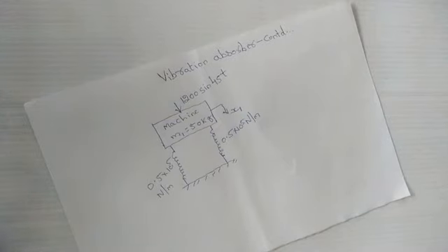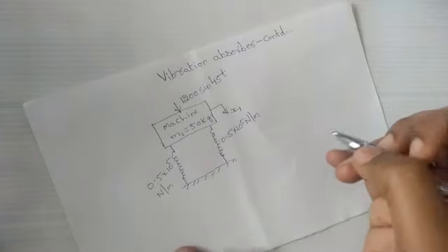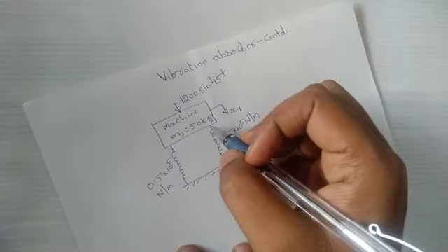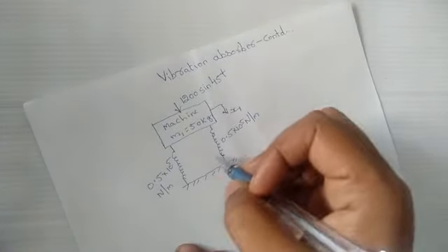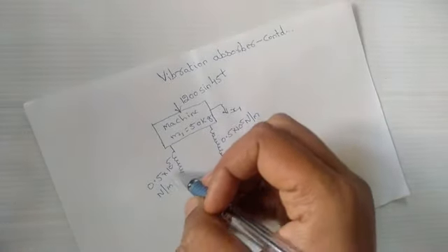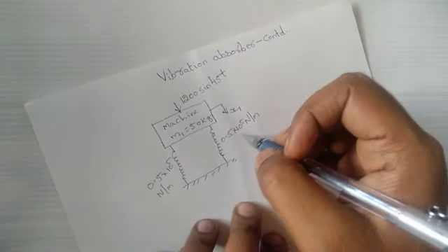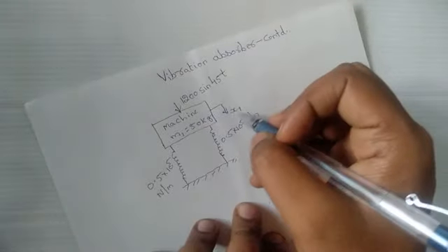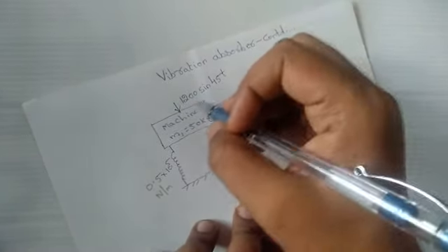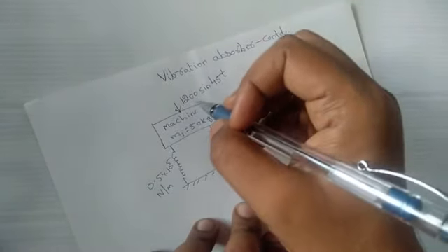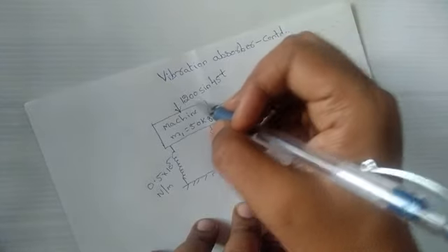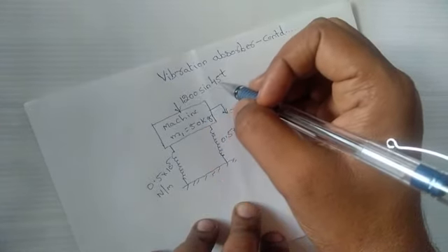In the last class we were discussing this vibration absorber. So let's continue this discussion. This machine has a mass of 50 kg with two springs, each 0.5 into 10 power 5 Newton per meter. X1 is the displacement. There's a forced frequency which is F0 sine omega t, which is 1200 sine 45 t.